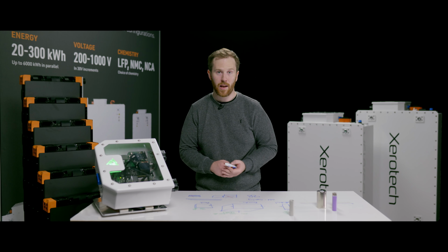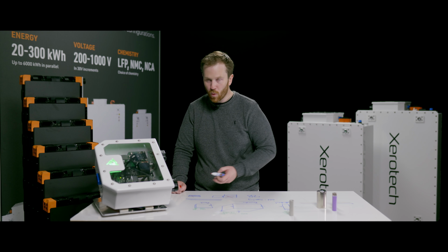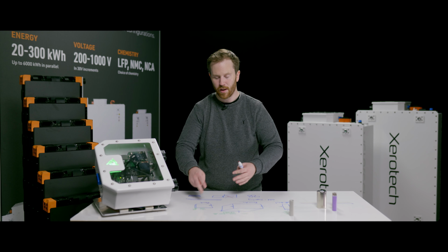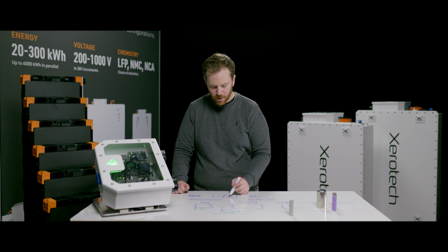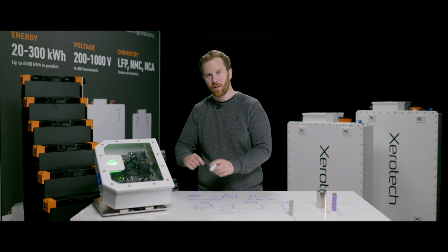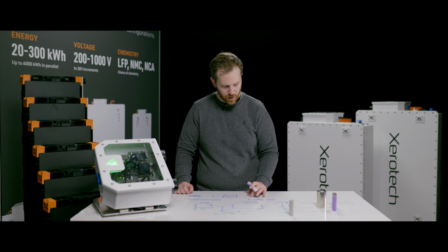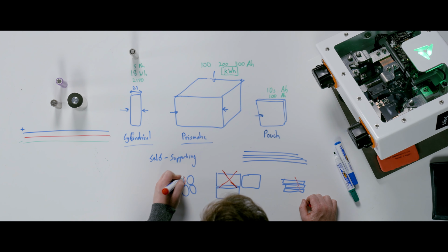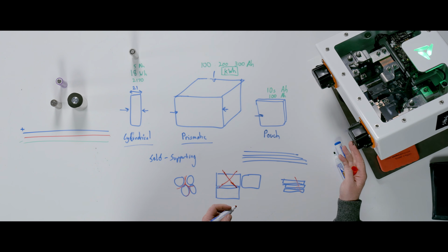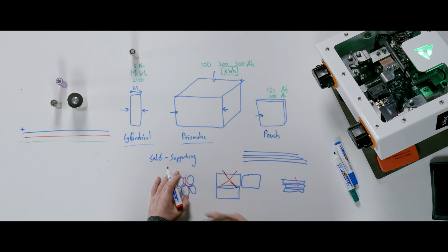So our advanced foam, passive propagation resistant design, other fire insulating materials will really struggle to contain kilowatt hours of thermal energy being released into the pack. So that's one consideration for large cell formats, is to make a passive propagation resistant design. So something that doesn't have a domino chain reaction inside of the battery pack. Cylindrical cells are great because they're manageable in terms of that. And also you can easily insulate around them, for example in the Zerotech design, with a structural fire retardant foam.